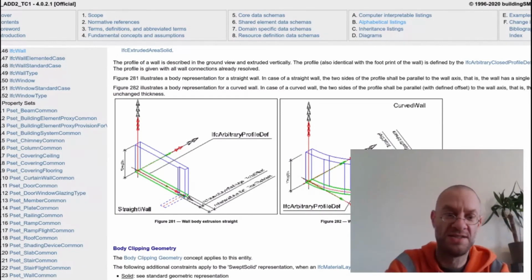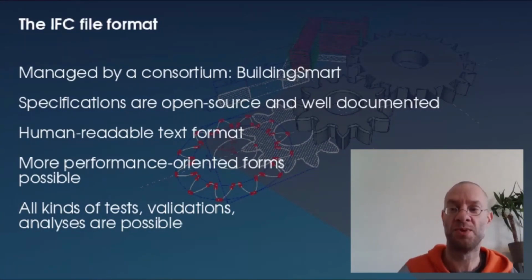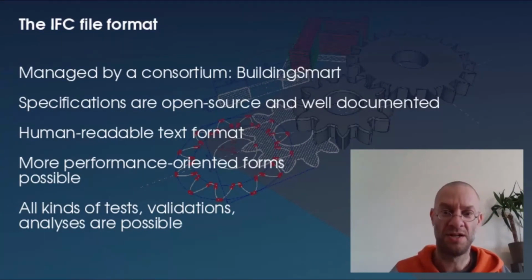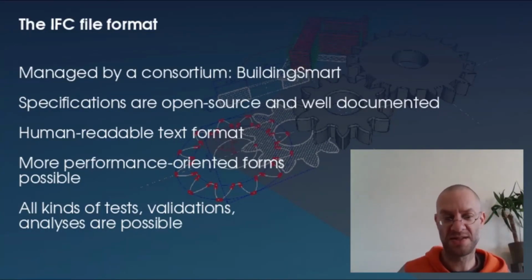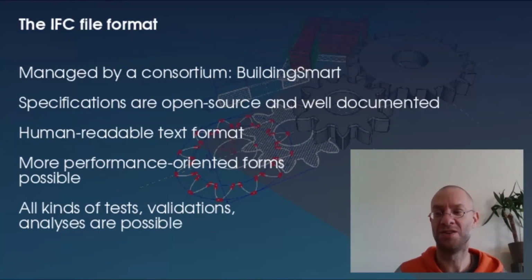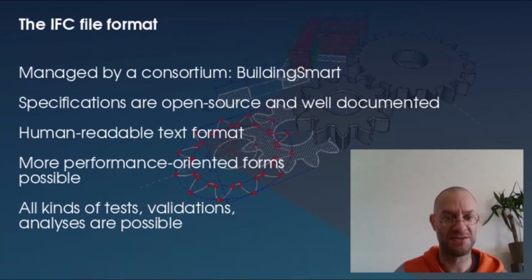And the IFC format itself is a text format. If you don't have any BIM application to open an IFC file, you could open it with a text editor, and you could read the lines inside and understand what's going on. You could very easily make a little program to extract the information that you need from inside an IFC file. It can even be rendered in a spreadsheet form, so you can look at an IFC building in a spreadsheet application. Have the quantities of doors, have the quantities of walls, etc.